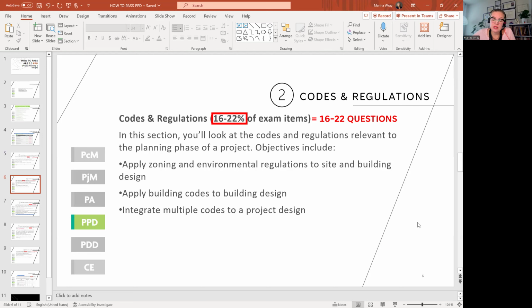And what this means is, for example, the height and area regulation. So if your client wants to have a 20-story building, but the jurisdiction only allows 5, you definitely need to get back to your owner and say that we cannot really design a skyscraper here just because there are height regulations here. It is by the airport or something like that. So you always need to communicate that to your owner when you get this information from the authority having jurisdiction.